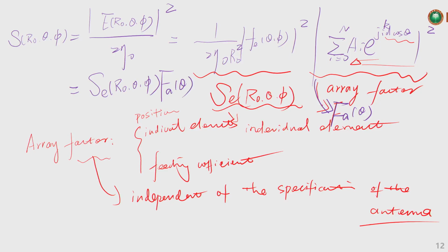So it looks the same as previously, when we wanted to write the expression for the power density of a single antenna, S_max times the normalized intensity, right? Like this one. So for antenna arrays, it's also the same form, even though the expressions for each parameter are different.